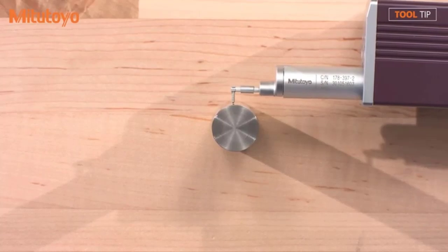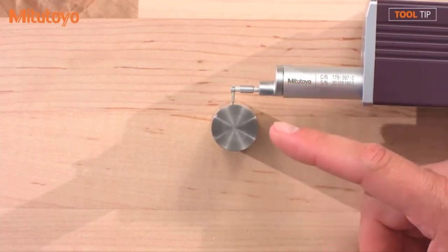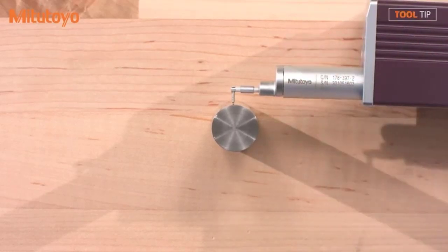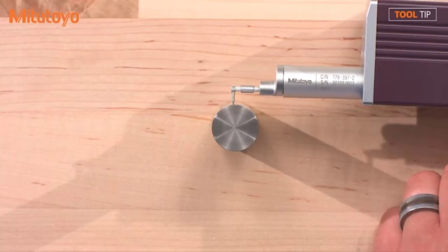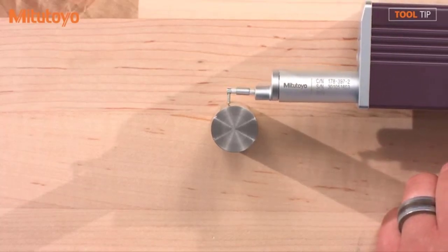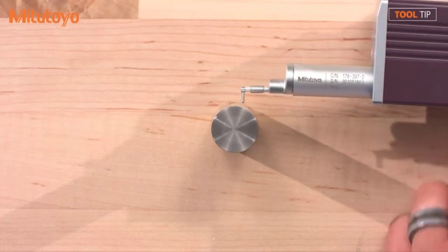So as long as I stay within the stroke of the detector. That's correct. Depending on the unit you have, that will vary how much actual stylus travel you have. So as long as I stay within my stylus travel, I can measure radially across the part. That's correct. That would be no issue to actually have the stylus traverse from side to side. Obviously, I'm moving the whole drive unit here, but in an actual measurement process, it would just be the detector moving the stylus.